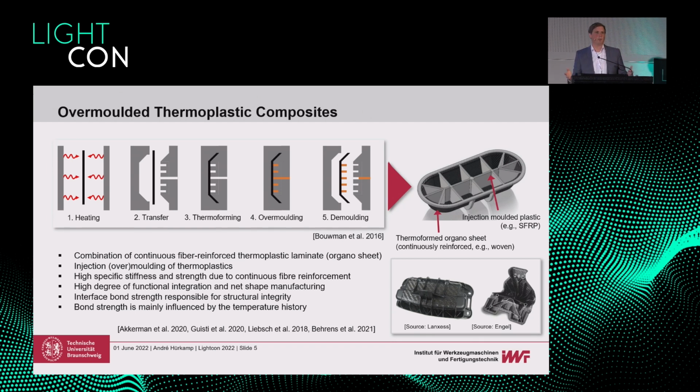And everything can happen on a single injection molding machine, which makes it quite efficient because we have a high specific stiffness and strength due to the continuous fiber reinforcement, and we can also integrate a higher degree of functional integration due to the injection molding.